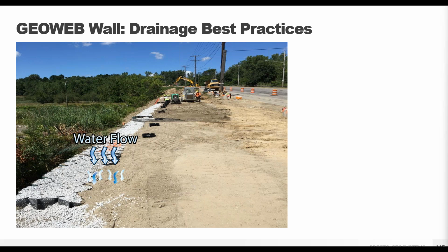The material used in the construction of the wall will have to be sized for the task, so using an aggregate mix with very low fines content can be a good choice. Sandy soil mixes are also good for drainage. You want to avoid using clay or silty soils, which will impede drainage and cause pressure buildup behind your GeoWeb walls.